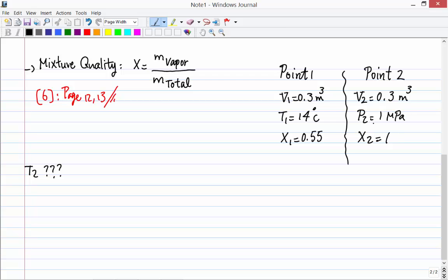We have pressure, and we know that the whole mass is vapor, and it's saturated because as soon as it got to this phase, vapor only, we closed the valve. So it means right at the saturated vapor, we stopped it. We didn't go to superheated. We didn't add heat any further. We just stopped at the saturated vapor phase. Therefore, this information is enough, right? I can find the exact point on the table.